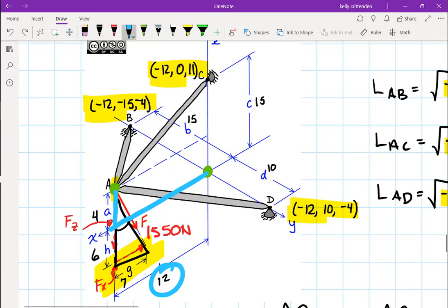And then for the Y direction, I didn't actually change anything because I just moved the coordinate system in the XZ plane, so all the Y values stayed the same. Here, the Y direction for point B is shown to be 15, which is in the negative Y, so it stays a negative 15. So it's only the X and the Z coordinates that changed, and basically all of the pins where the coordinate system started were at X equals 0.